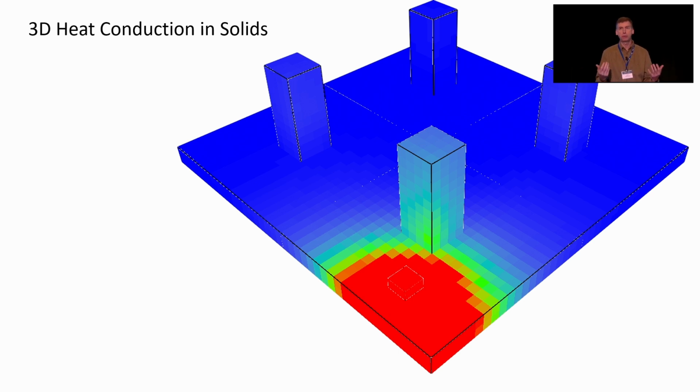Well, it's always been the strategy in FDS to use a simple one-dimensional heat conduction calculation normal to the surface, because when we're doing fire simulations, most of the time the solids that make up the boundaries of our computational domain tend to be relatively well insulated. If you look at this room, for example, the wood, the plaster, whatever else this room is made up of, it's not highly conductive.